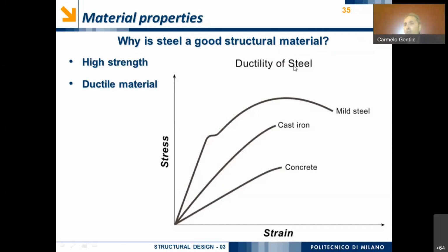In addition, in order to have a brilliant earthquake behavior, this is much easier to obtain for steel construction, because I have just to avoid buckling, than for reinforced concrete, because in order to obtain a very good behavior for concrete structures, I have to use some very significant details.